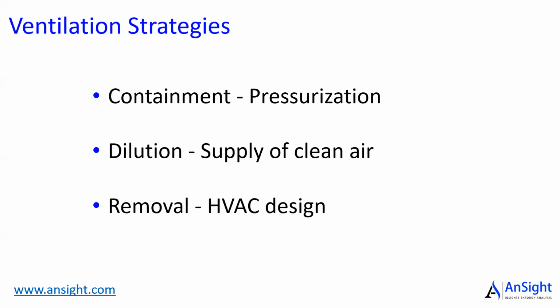The second strategy that probably most of you know is dilution. You supply clean air to the space and try to dilute the contaminants in the space so their effect, especially in terms of exposure, can be reduced. And finally, once you supply the clean air, it meets the sources of contaminants and the clean air gets dirty. We need to effectively remove the dirty air from the spaces.